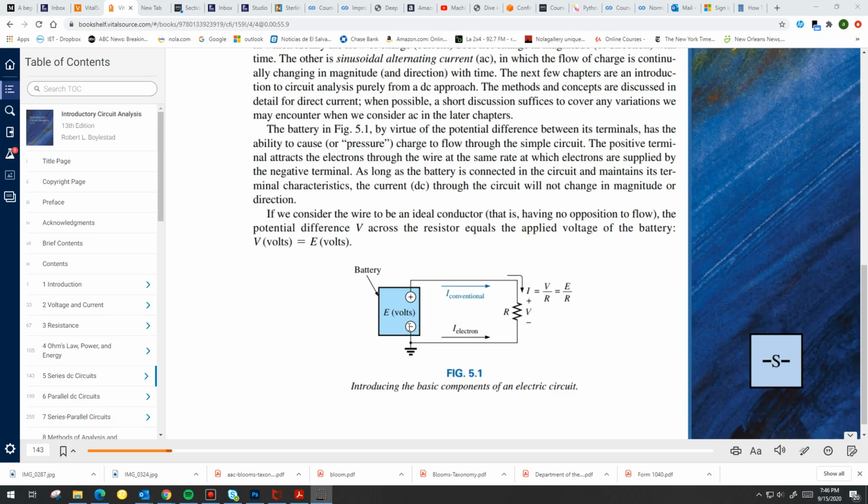The important thing is that you be able to follow the path for each of the elements in the circuit. If we start with the bottom here, where this is the ground symbol, the ground is connected to the negative of the battery. The positive of the battery is then connected to one end of the wire, and that wire goes to one connection point of the resistor.